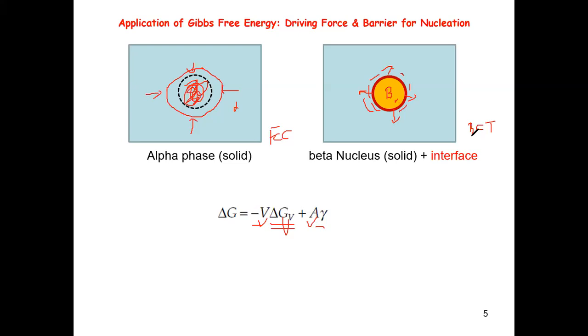The reason is that we assume we have a perfect coherent interface, so on the interface, atoms still have pretty good adhesion among one another. In this case, after the transformation, the beta phase wants to shrink, but the alpha phase constrains the shrinkage. So the beta phase is going to pull everything. This also causes a tension field near the beta-alpha interface.